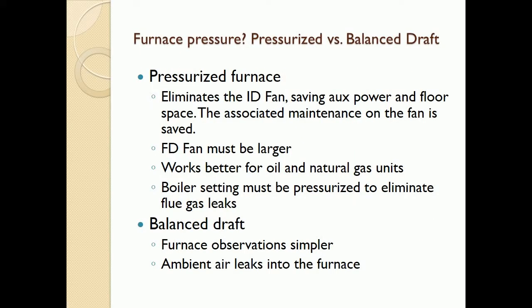Furnace pressure. Pressurized versus balanced draft. A pressurized furnace eliminates the ID fan, saving power and floor space. The associated maintenance on the fan is saved.